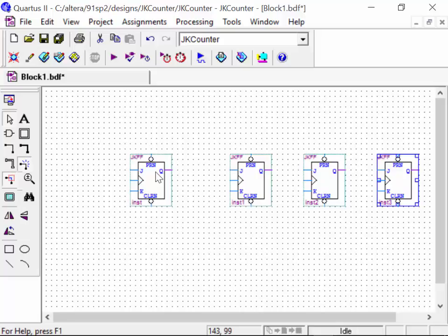You notice that they have bubbles on them, which means that they're active low. I mean, we're going to tie them to VCC. We want them to be tied high. I said ground, but in this particular case they're active low, so we want to tie them high. If we pulse them low, and I'll do that in my diagram, you'll see that our outputs all go to 0 or to 1 immediately. So I'm just going to go ahead and tie everything to VCC.